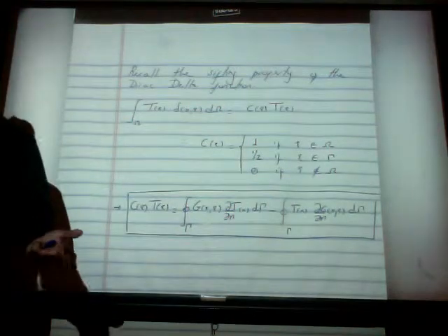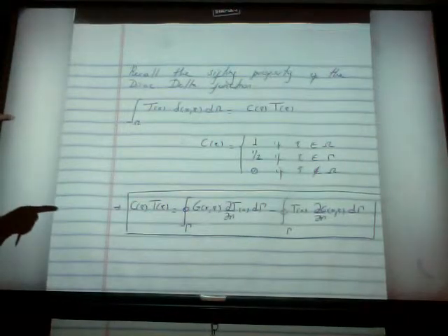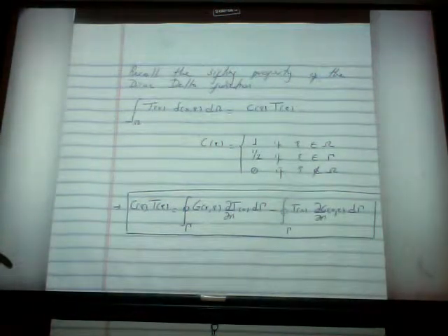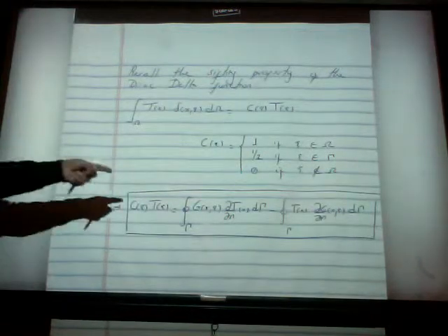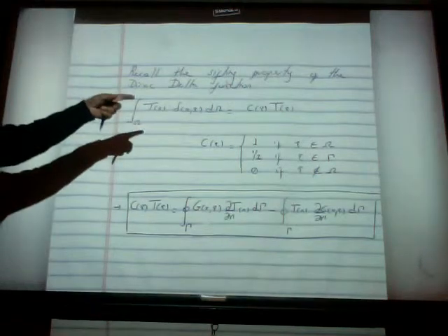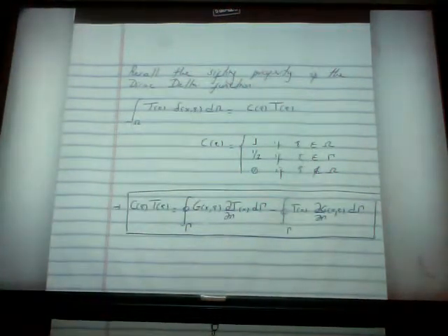So the problem is solved, okay? Except for something. First, we don't know the temperature and the flux everywhere. We know the temperature somewhere and the flux somewhere else. And also, we don't know g yet. We know that the Laplacian of g is equal to the Dirac delta function, but we don't know what g looks like. We need to solve for g, right?